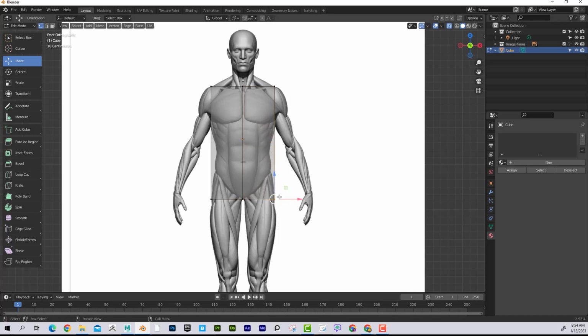And I'm going to drag over these corner vertices and move it up. And you can see that when I move it up, I actually want it to be the same on the other side. So if I wanted to do that, I could go up here, and I can see that I could try X, Y, or Z. I'm going to try Z, let's see. And if I move that, okay, nothing happens. If I have X, now when I move it, it does the same on the other side. That's going to be good for a little bit, but I'll show you actually another way that we're going to mirror using a modifier.